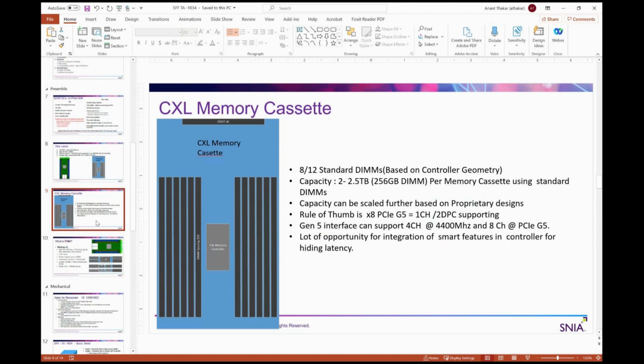Now, another interesting thing is the CXL memory controller. As you said, there's a lot of discussion on the IO side and performance side, on how we improve the caching capability of that. There are a lot of solutions people are already thinking about: I don't really need to read from the DIMM itself. I have enough caching capability on the CXL memory controller, and I can turn the transaction back much faster to the host side. So this is the benefit which is going to come. The more you try to put in the E1 and E3, the ability to add caching and all other things is going to be extremely limited because the form factor is extremely limited for that.